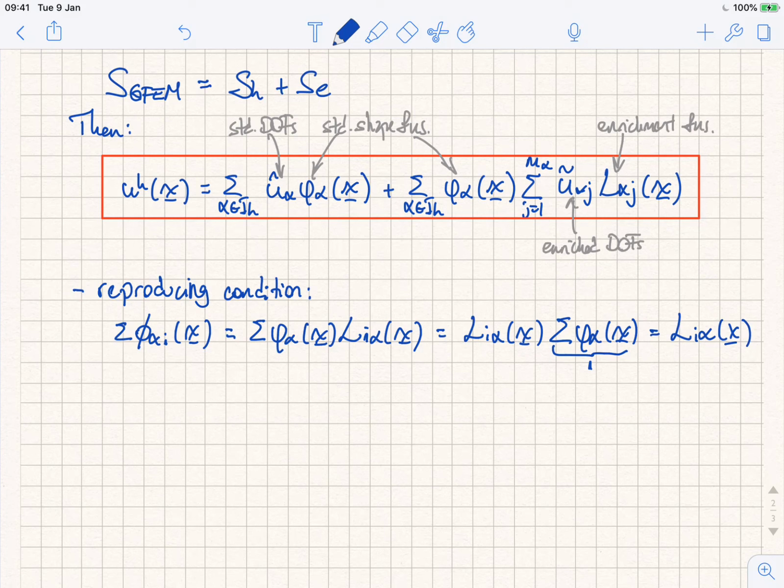And the other thing that you can think of is that by doing this type of formulation, you are pasting local types of approximation together, right? We saw a cloud and we said, well, what if we multiply the shape function of that node by some function? Well, the behavior is localized in that cloud. The cloud next to it could have a different behavior, could have another function, right? And so you can think of this method as really pasting together different approximations in different clouds of your domain.